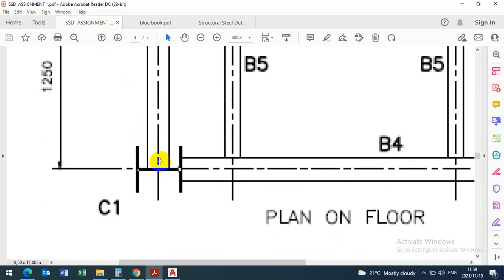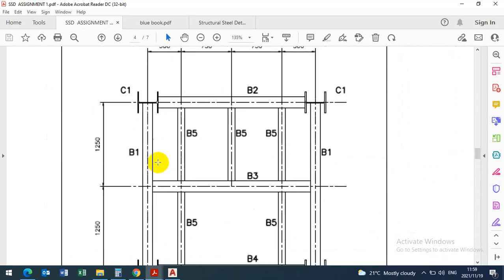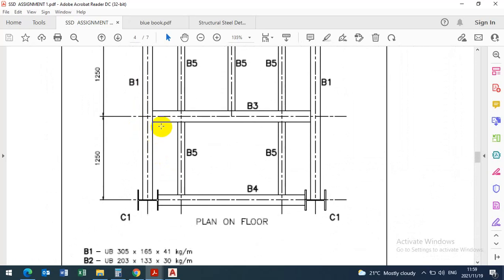That is what they will cut. Okay, so we need to know what is beam 1. Then coming to this other connection here, I've already mentioned that beam 3 is coming into beam 1, where you need to notch beam 3. We don't notch beam 1 because beam 1 is the main beam.